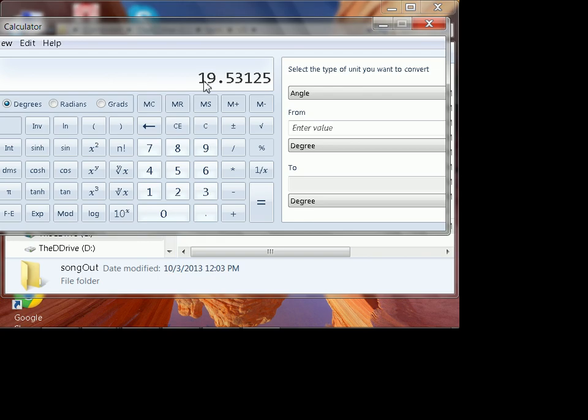And the microphones can play directly through the speaker. So if you make your laptop listen to the microphone and play it directly to the speaker, you can take the headphone output from your laptop and plug it straight into the Arduino Uno. Slick, right?